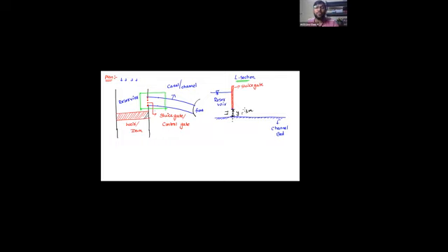So my dear students, what is meant by steady flow? At this particular section, when I open the gate, some amount of water will flow. And it must be having some velocity. It must be having some depth of flow. As long as I don't operate the sluice gate further, the flow velocity and flow depth remain the same at this particular section with respect to time. Such a flow is known as a steady flow.